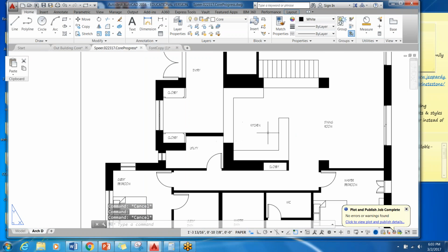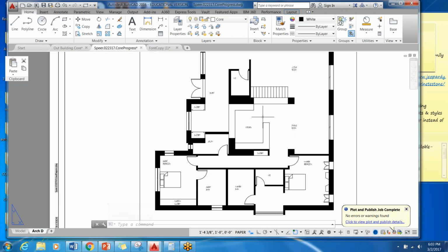So I know from Shemaine's work, we measured this text and it was 6 inches. But what does that even mean to me when I go to print at a 1/4 inch scale? So you remember from hand drafting, sometimes you would use your architectural ruler and you would set up your top line for the text and the baseline, and then you would go within them to create a certain height. Annotative is basically that. It's the most precise way to know exactly what height in inches you are drawing your text for when you're going to print. I'll show you the difference.